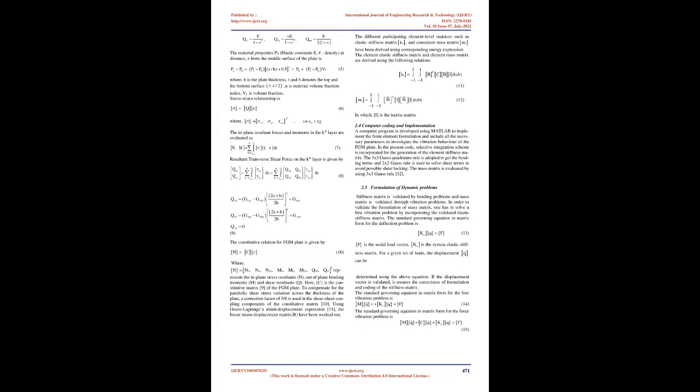The analysis was carried out for a C-SiC FGM plate with different volume fraction indices. The results are compared with Abaqus CAE by using S8R5 shell elements. 2. Problem formulation. First-order shear deformation theory is used for plate formulation.